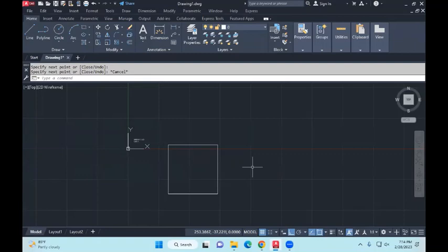The next thing I will do is, by the way, I've shown you guys how to erase things, how to delete things. If I have a line, that's another command, an easy one. Either you can use the erase function. Erase removes objects from the drawing. That's erase, simple.